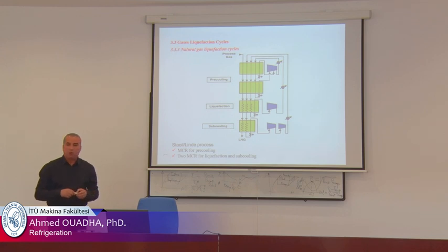Another remark: we have seen for the application, for example, in a throttling valve, that the enthalpy is constant in the throttling valve, and normally the temperature will decrease. But for some applications in cryogenics, the temperature may increase in expansion. It depends on the initial temperature. The Joule-Thomson coefficient may be equal to 0, less than 0, or greater than 0.